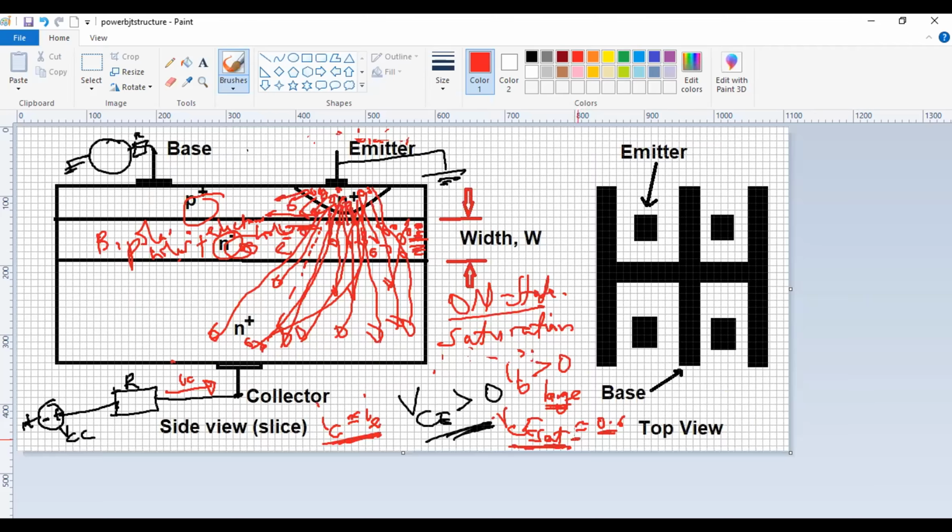So it's another thing to remember, that the voltage drop is going to be greater, mainly because you have the lightly doped area at N minus. You're going to have a larger voltage drop, but because now you're able to block a much larger voltage when it's in cutoff, we can take that as a benefit. So we can do that trade-off: this will be larger in terms of voltage drop when the switch is on, when it's in saturation.